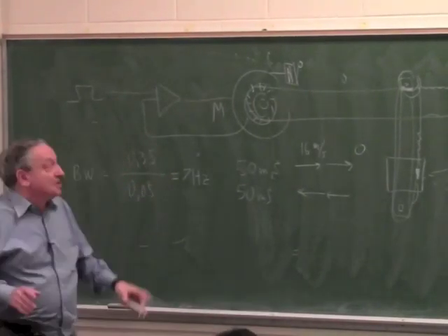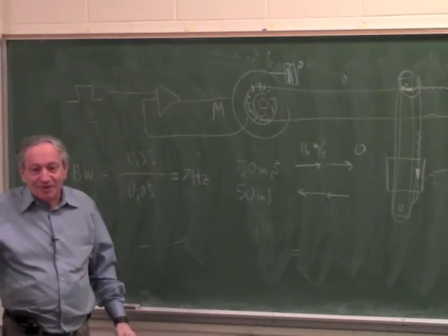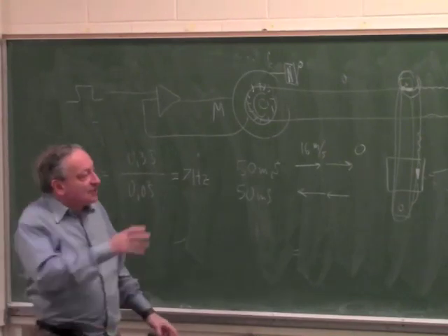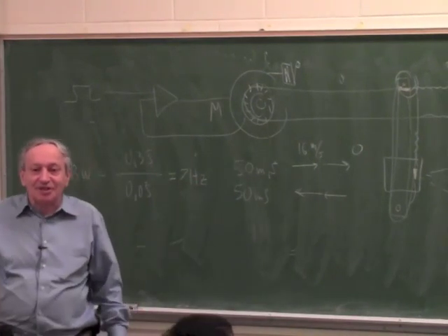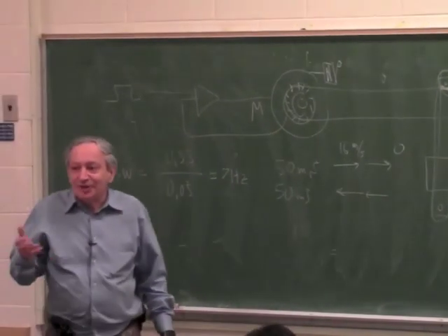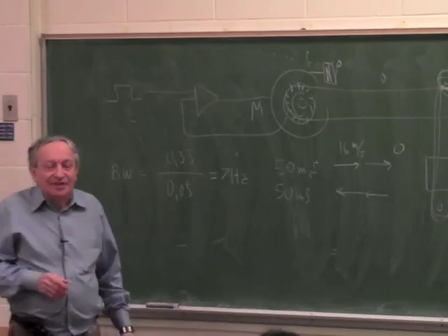Okay? So this whole process, these are steps you take in a servo system design. This is not how to do the servo itself. Of course you have to write code for the servo, that's a different problem. This is just, if you're given a spec, how do you convert it to parameters you look up in a data sheet? How do you convert it to bandwidth? How do you convert it to power, to force, to accuracy? Is that clear?